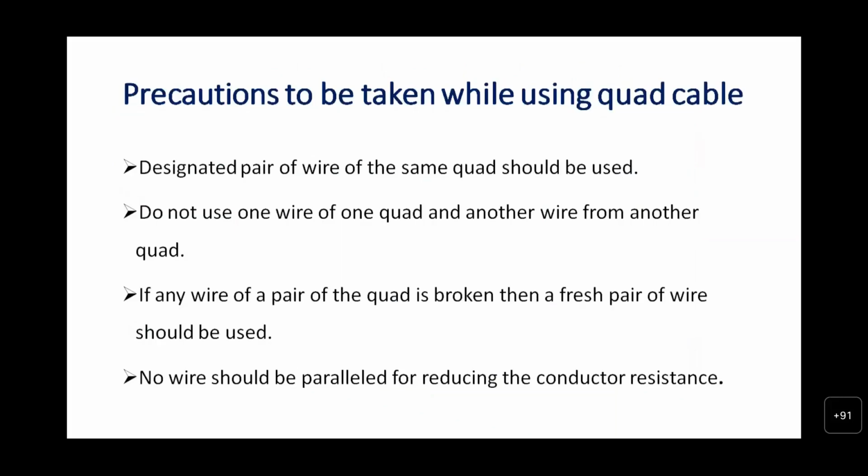Precautions to be taken while using the quad cable. The designated pair of wires of the same quad should be used. Do not use one wire of one quad and another wire of another quad. If any wire of the pair of the quad is broken, then a fresh pair of wires should be used. No wires should be paralleled for reducing the conductor resistance.